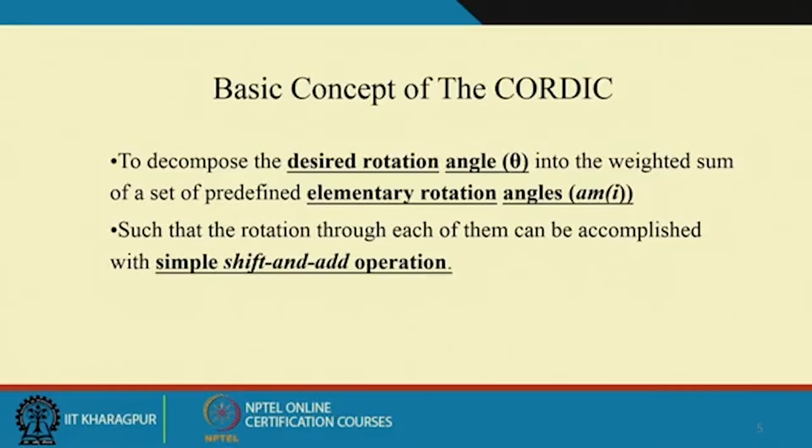And the beauty of this is that while calculating the sine and cos functions, only shift and add operations are required. I do not need any multiplication, and the operations are much simpler.